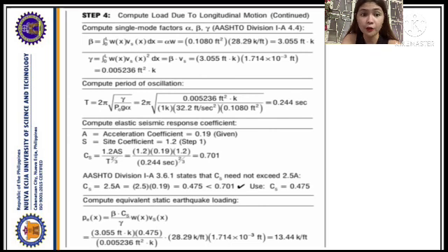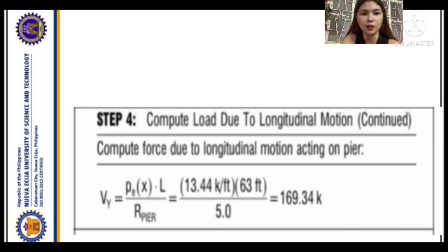Note, the earthquake force from the superstructure is transferred only to the fixed bearings. In this case, only the center span load is transferred to the pier in the longitudinal direction. In the transverse direction, however, we assume all bearings are restricted, guided bearings. The diagram in the accompanying calculation sheet illustrates the bridge under longitudinal earthquake loading with the static displacement depicted at the pier location. In this calculation sheet, we determine the value of the alpha single mode factor.